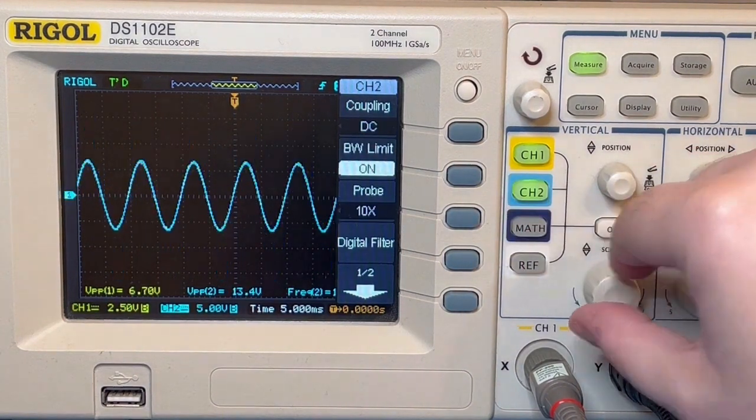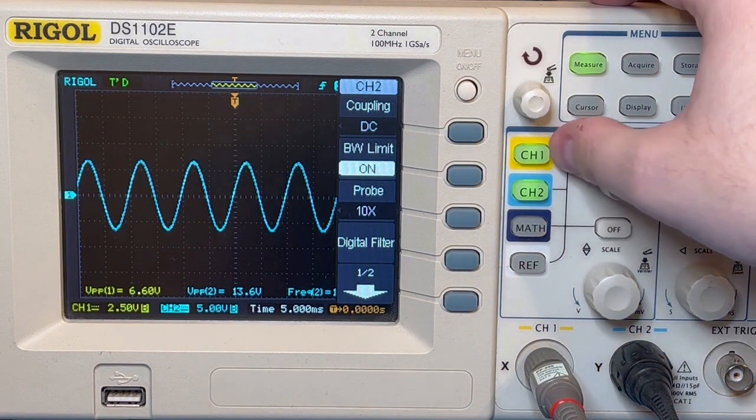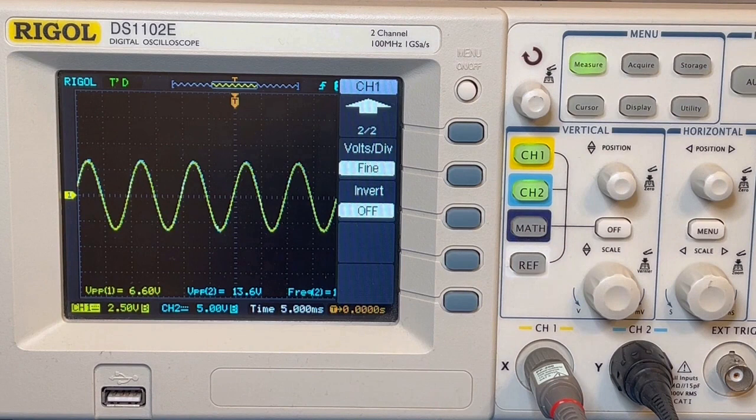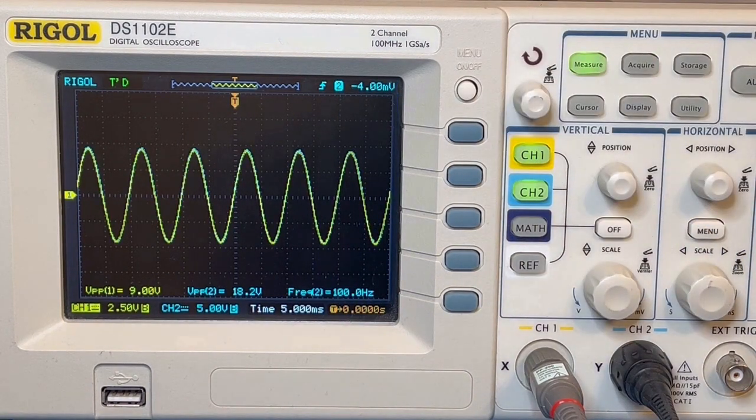Now I'm going to stop changing the scaling factors and keep the two channels at a factor of 2 apart to negate the gain of the amplifier, so that the two channels' signals appear on top of one another. Now we increase it further. Before, it was about 10.8 volts where something started to happen, and so if we assume it's roughly symmetrical on the other side, the volts peak to peak should be about 21.6 when something strange happens. So let's see what happens.